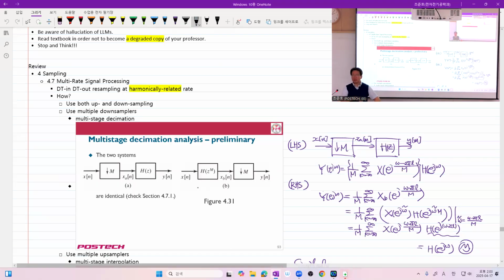And you may say that, oh, something's wrong. Well, usually when we talked about a downsampler, the filter preceded the downsampler. So we had a filter, usually an anti-aliasing filter, and then a downsampler. But here, be careful. To use this equivalence, you need to identify a downsampler and then a following filter. Got it? So this is significantly different from what we already know as common sense. Now, even though the convention is to use the Z transform of the filter, we know that under certain conditions, it's okay to use the frequency response of the filter, right?